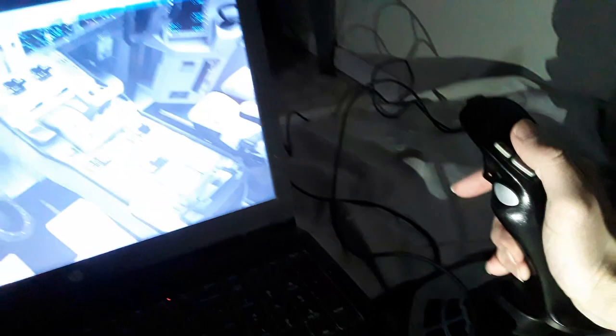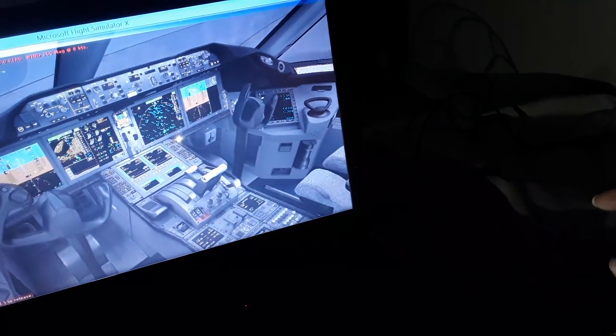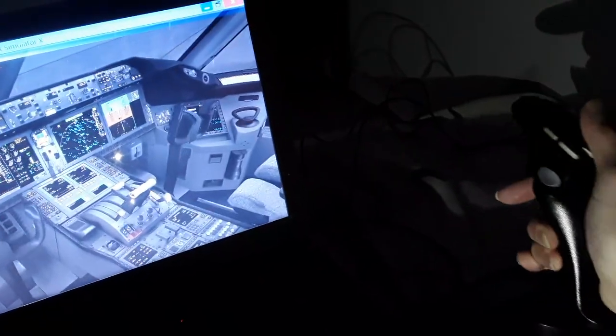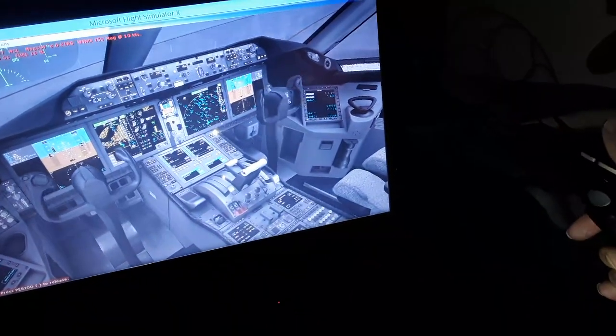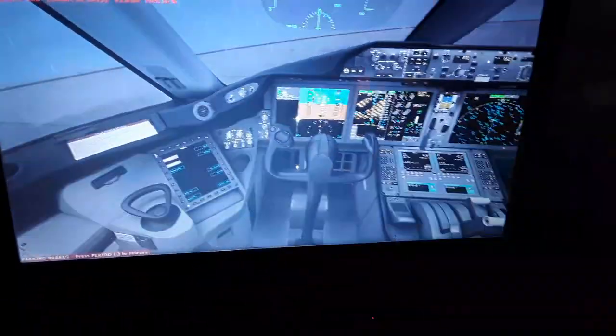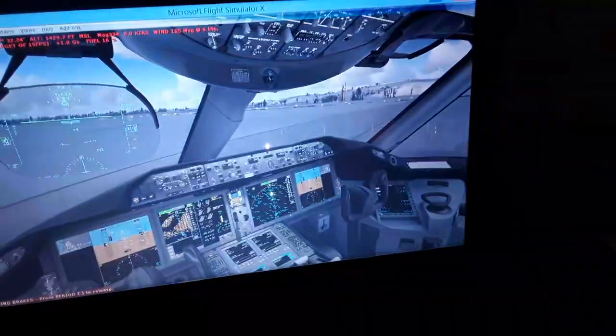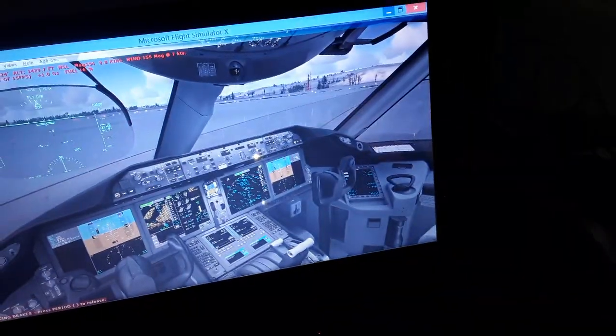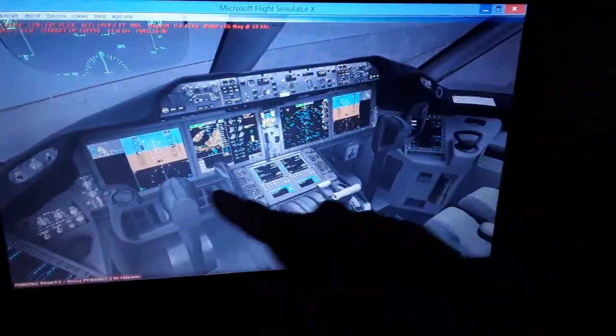I have the side stick, the Logitech Extreme 3D, which is the Airbus identical side stick you can use for climb descent, and also make left turns, right turns, side stick left and right. This is the control wheel of the Boeing 787. In the yoke of the Boeing 787, the control column, you can make climbs and descent, pull the elevator up and down. Also the rudder pedals, which are also interconnected with the nose wheel steering, the tiller over here. So you can use the nose wheel steering also to control the aircraft, and also have the vertical stabilizer. You have the toe brakes also over here.